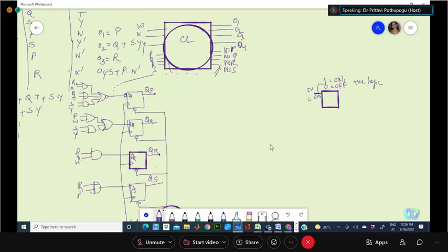So here what we are saying is whenever we switch on the system, or any unwanted spike is happening in your design. A spike is nothing but 0 to some 5 volts, or plus or minus of this value. An abrupt increase in the voltage may give a false indication to this design, which is positive logic, as switching on the flip-flop or switching on the circuit, where it is a noise.